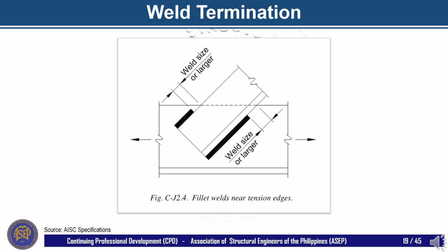Fillet weld terminations in most cases do not affect the strength or serviceability of the connections, but in some cases, the disposition of welds affects the function of the connection, and notches may affect the strength and the resistance to crack initiation for cyclic loads.